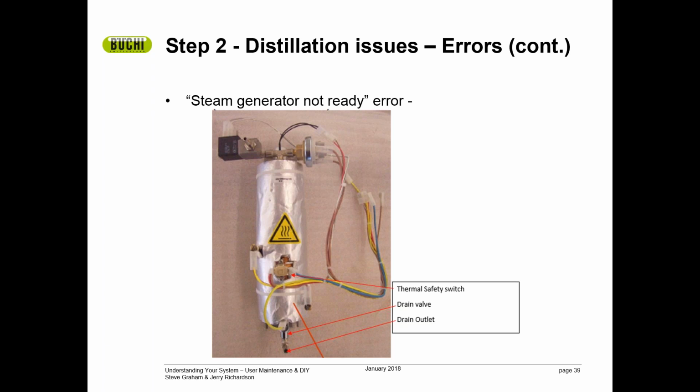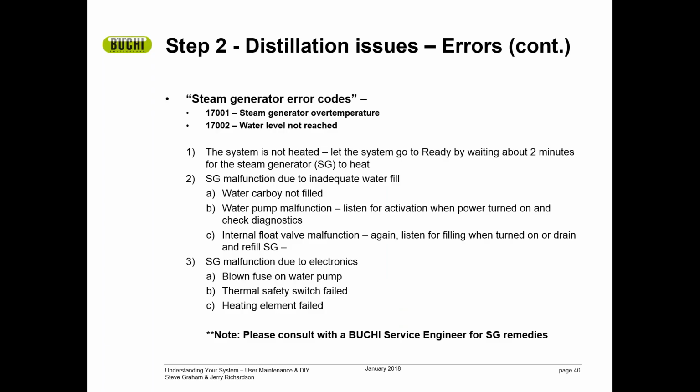After you do this, close the drain valve and turn the system back on and listen to the system. What you should hear when you turn the system back on is the water pump should be activated and it should be filling the steam generator.